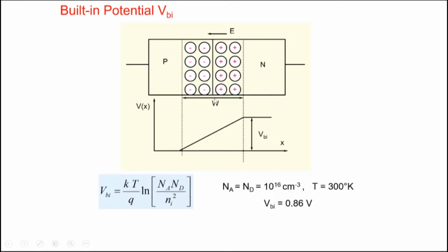Okay. So there is a built-in voltage inside the PN junction, this electric field there. And the presence of the electric field or the potential here is what is preventing the carriers from moving from one side to the other side. So note that there are holes here, and they would like to move because of the concentration gradient to the N side. But note that the hole will see a potential barrier here. The hole has to surmount this potential barrier to come to the N side here. And similarly, the electron sees a potential barrier here.